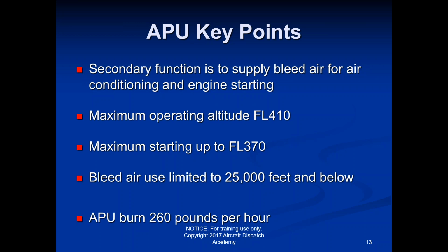It's called an air-driven generator. Yeah, it's called an ADG. We do test flights a lot for ADG drops. You probably hear about them. It usually requires a check airman, but an ADG is like a fan that has these big steel fan blades on it, and it's directly underneath the cockpit. In an absolute emergency situation where you don't have any electrical power at all, no engine generators, no APU generator working, they can pull this lever, and below the cockpit it drops down this fan, and then it hits the air and makes it spin like a windmill, same idea as wind power, but it drops down and it's really loud.